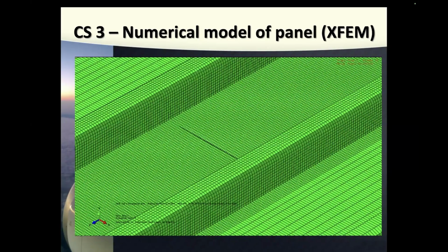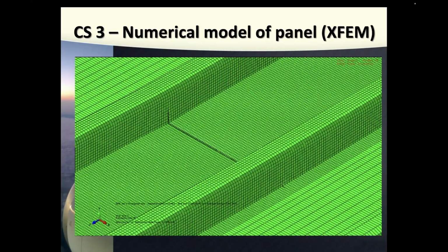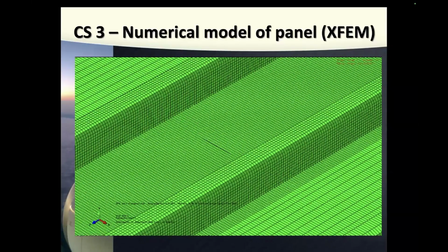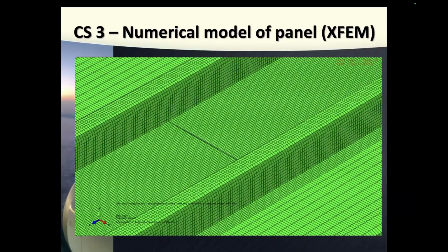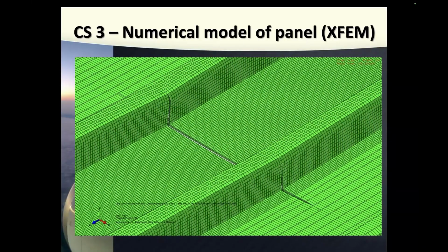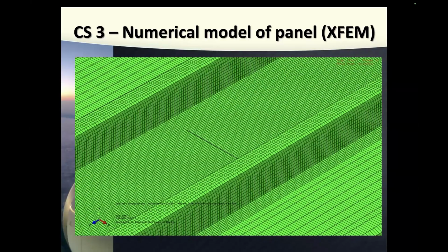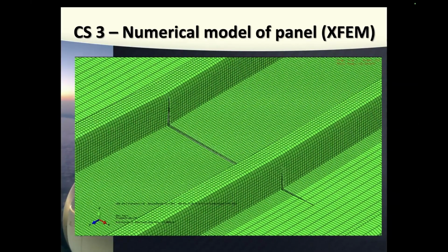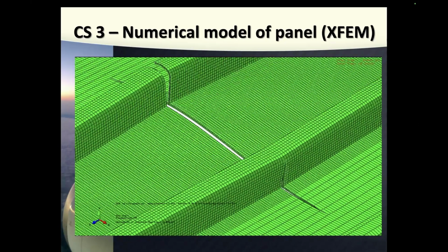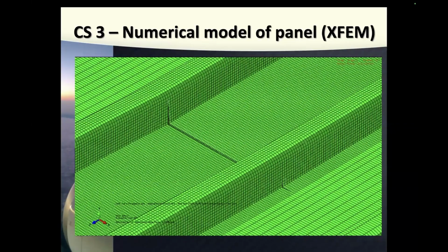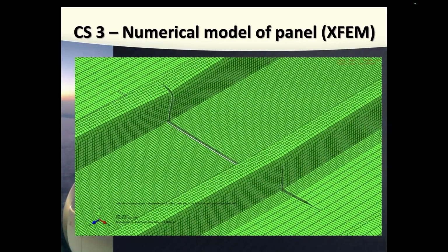It works. Yes, we can see how this crack is growing and then destroying the first stringer and then partially the second stringer. But in my simulations, I managed to break all four after 100 attempts, because it's about mesh density, boundary conditions, and defining the step of the growth. There are many parameters that you can control and define.